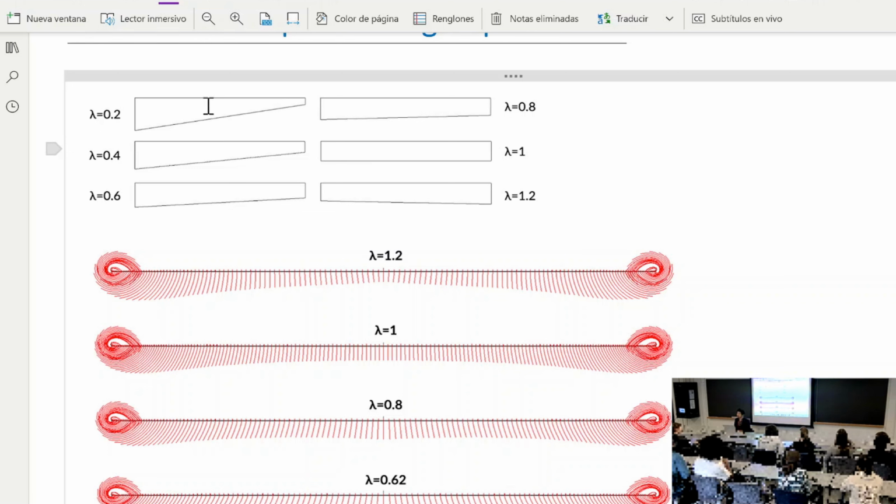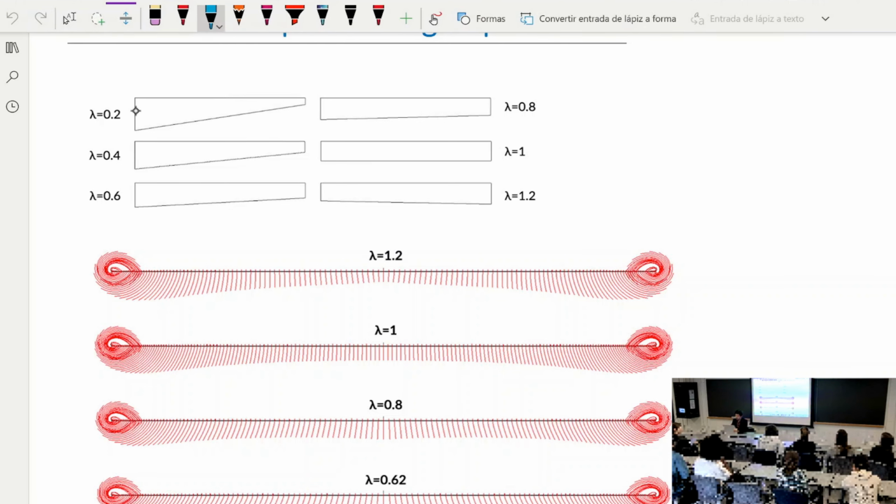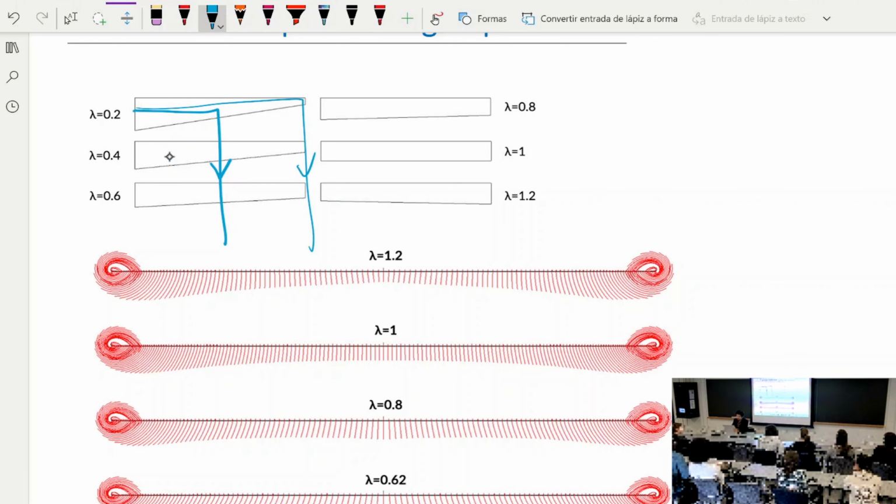And because of the multiple pairs, some of the trailing vortices start not from the wingtip, but from the inboard side of the wing, right? And the result of this inboard trailing vortex goes that way if we look from above. As a result, the induced flow of these kinds of vortices induces a downward flow over here, but an upward flow on the outside, right?